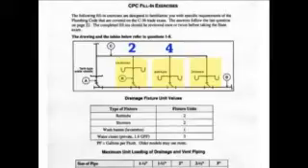So we have 2 for the lavatories, 4 for the bathtubs. That'd be a total of 6 right now. What do we have for the showers? The showers have fixture units of 2 each. We would have 2 plus 2 would have 4. So we have a total fixture unit on the C area pipe of 10 units. 10 would be the answer for number 5.